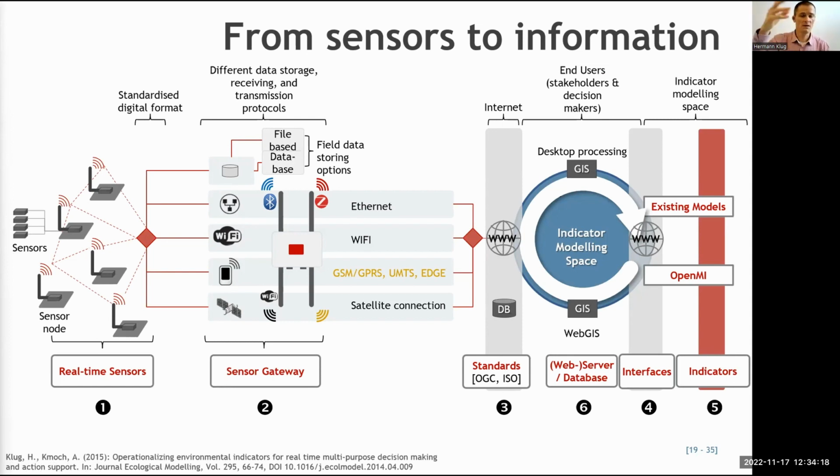So every 7 kilometers, I could be connected to another station to transfer the data sets. What we did is we stored all the sensor data in a 10 minute interval at the station, but at the same time we were sending it to one hub also connected to the internet. This was a mini computer, a Raspberry Pi, at that time 35 euros, collecting all the data from the stations, storing them, either file-based or in a database, and at the same time we were sending this information via SIM card to a cloud service.